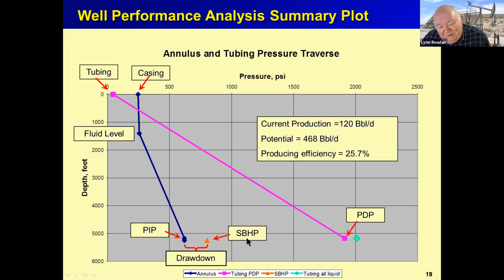And then this is the pressure inside the tubing, and so here's the pump intake pressure, and the pump raises the pressure at the bottom of the tubing to discharge pressure by some method. This is probably a rod pump well, probably just compression. And then the compressed fluids flow from the pump discharge all the way to the surface to this tubing pressure, which is probably 80, 90 PSI, not very much.